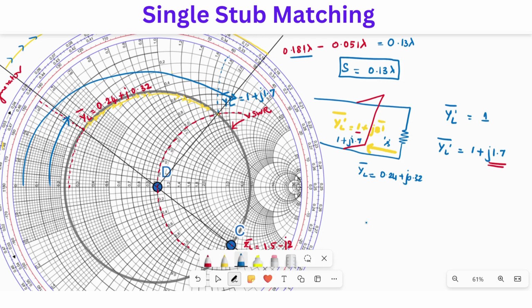If we provide a negative susceptance which is minus J 1.7, then when we add these two values we will get YL bar equal to 1. So our stub should provide minus J 1.7.